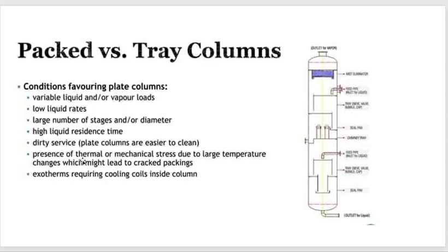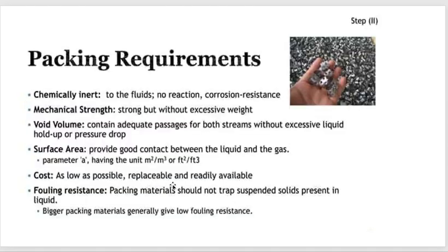The presence of thermal or mechanical stress due to large temperature change might lead to cracking or something like that. Here there is more control related to the temperature using side stream, side reflux, and something like that. Okay, exotherm requiring a cooling coil inside the column, for sure we recommend the tray tower.